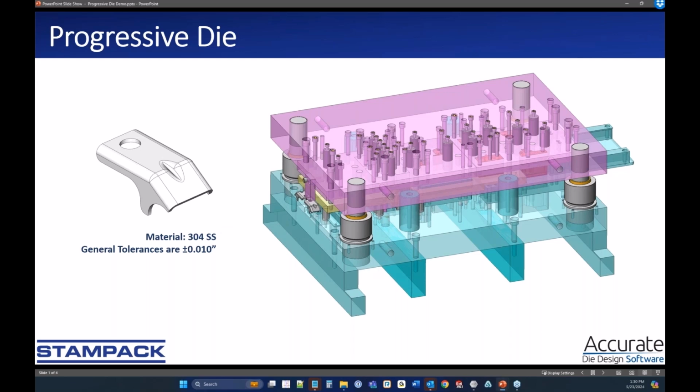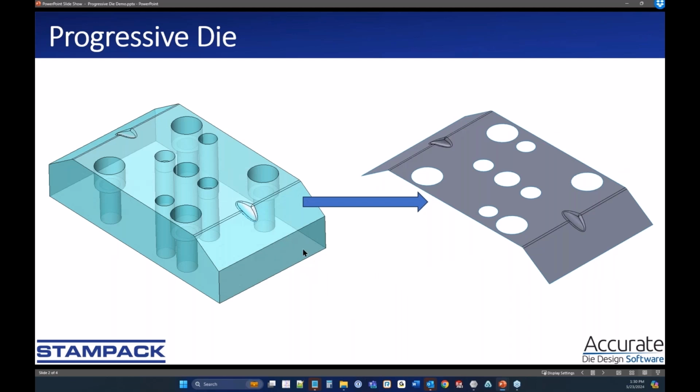And for what we'll show here inside of the Stampack software itself, what you'll see is that in your actual CAD design, you'll have the full 3D component, but inside of Stampack, we only care about having just the active surfaces that are going to be actually touching the tooling to the blank and actually forming the geometry. So when you see the geometry inside of Stampack, that's what we're actually working with here.